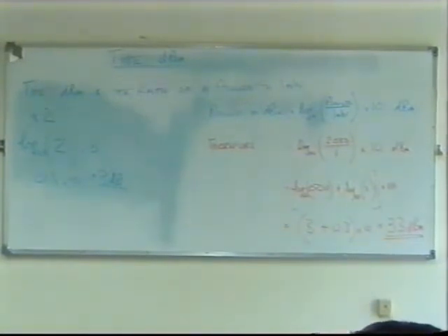Because they double. So the 3 dB is multiplied by 2, in that example. In other words, 3 dBs to the ear, not much difference. How much would the difference be? Well, probably you would say a 10 dB change in sound would be significant. You would hear that. Now, if you talk about 10 dBs, that's 10 to the power 1. In other words, if you really wanted a 10 dB increase on your 50-watt amplifier, you'd need 500 watts to make an appreciable difference.